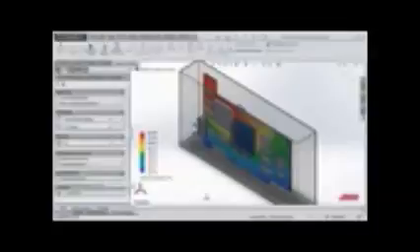If we scroll down and pick a component in the Thermal Analysis pane, it highlights on the selected goal window on the right-hand side. The selected goal starts to slowly converge, and after about 10 iterations, you really start seeing it ramping up. As it converges, the plot starts getting flatter and flatter as it goes to a converged solution.